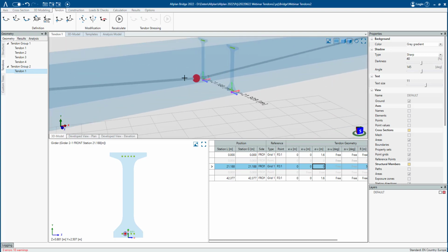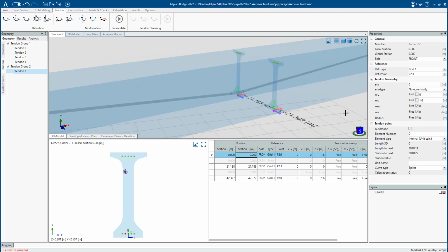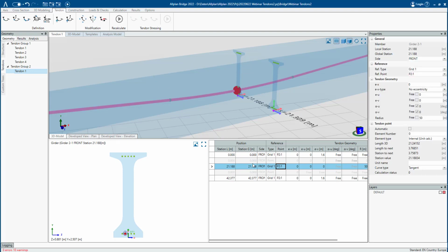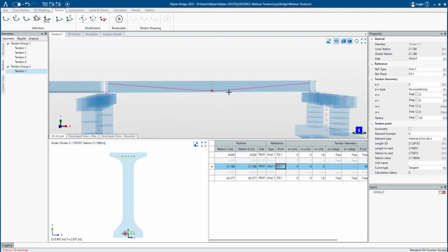And in this case, you can see that 2 points are also created along. There's this part in between with the 5 meter radius, and then it goes smoothly into the spline section here and here. Yeah, I can go in and say I want to adjust this. The radius is too small, I want a bigger radius of 50 meters. Oh, you can see here the 2 points, they go further out as the radius is fitted in a bit differently, with the intersection between the spline and the tangent, and the radius point getting further outside. Like this I can set it however I like, and now you can see it's not that V-shape, it has a rather curved form in place.